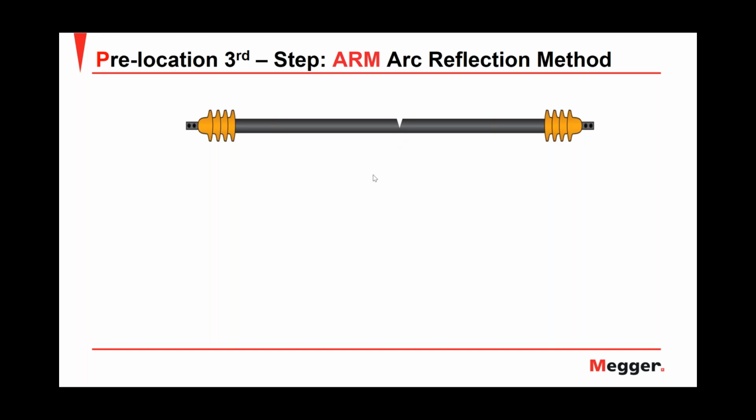Well, the first thing I will need is to use my TDR in my thumper to get the reference trace. And this is the reference trace. In the reference trace, I will have a change of impedance. The change of impedance comes from the test leads and the connection of the test leads to the cable under test. If we see this reflection, this change of impedance comes from the change of impedance between the test leads of my thumper and the connection between the test leads of my thumper and the cable under test. So this is the first change of impedance.